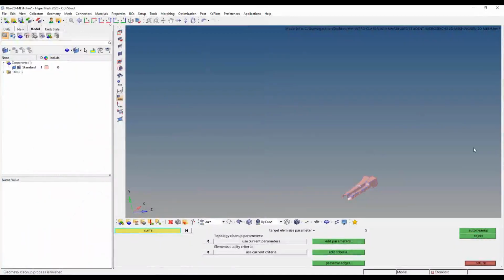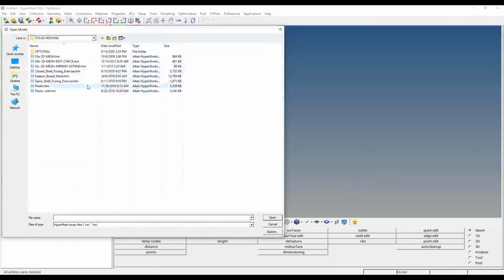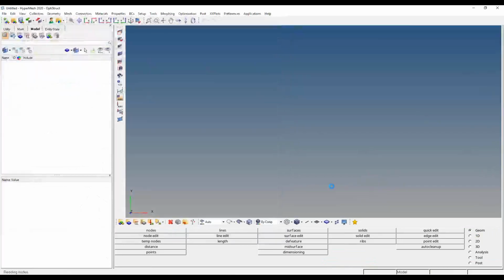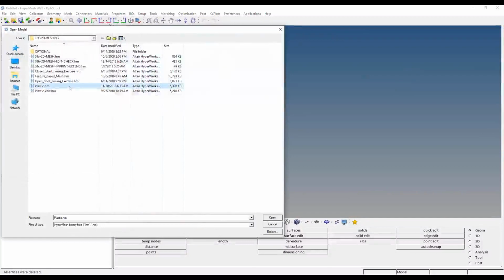Yeah, I'll just add to it, it's just the element qualities. It goes with your consistency. You want to make sure your warpage and Jacobians and all those things are in line to the standards that are needed for it. So if you're going to have pretty warped and bad elements, then that'll quickly cause problems.